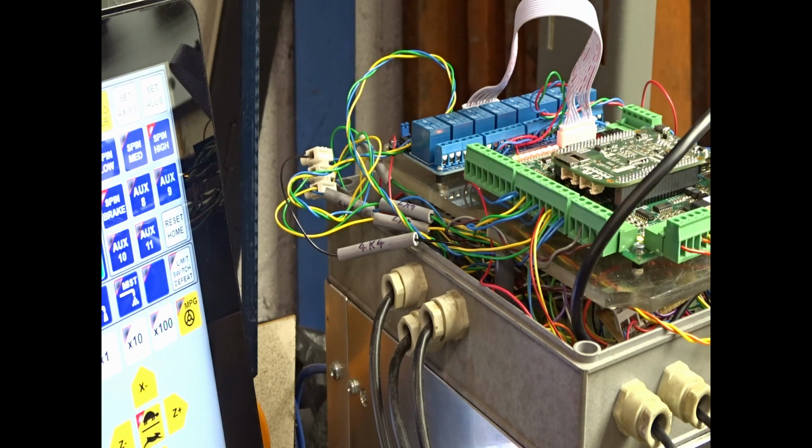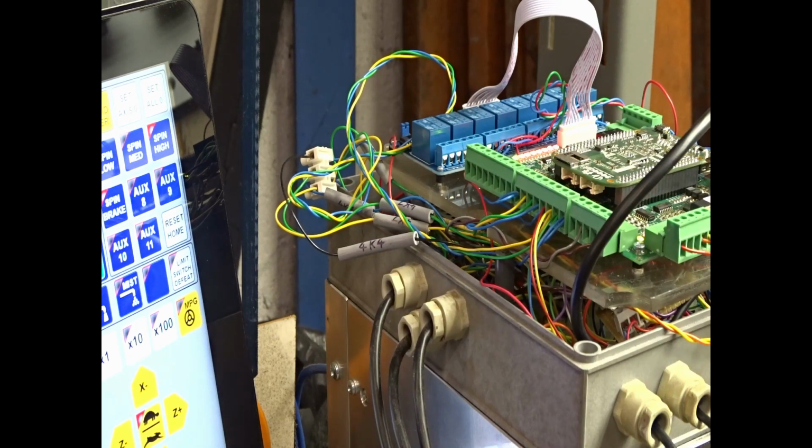So I'm going to drop them to the 3K or 2981 if you prefer. I'm going to do that for all 6 of them. So I need 12 resistors of 1.5K each. Solder them together or use ferrules, cover them in sheathing, write their numbers on them and fit them. And then hopefully we'll be within range and that problem should go away.